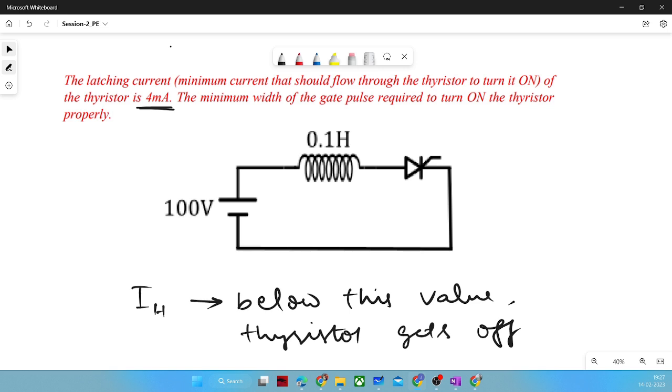See, thyristors are getting used, but not in inverters, the most popular ones. If you take the example of traction applications, now these days we are seeing electric vehicles and all. There we avoid thyristors because turning off the thyristor is a quite tedious process.